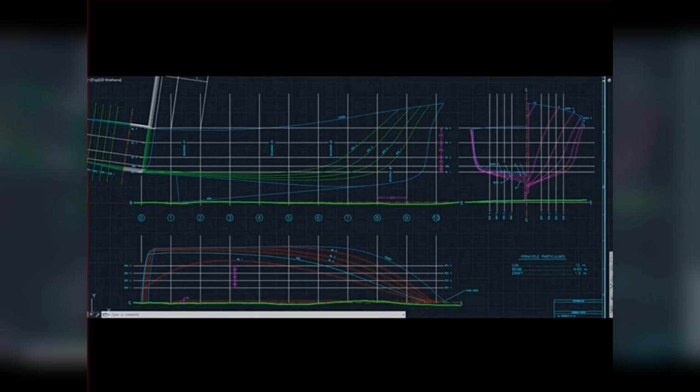You have to imagine where these lines are when you're looking at a ship. If you're looking at it from the side, of course, the baseline is at the bottom. If you're looking from the top down, the center line is right down the middle. And in the body plan view, you will see both the baseline and the center line. These lines allow you to take measurements to all the different points on the vessel in terms of the hull lines. So keep those in mind, they're pretty important lines.